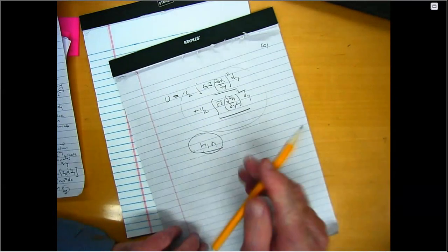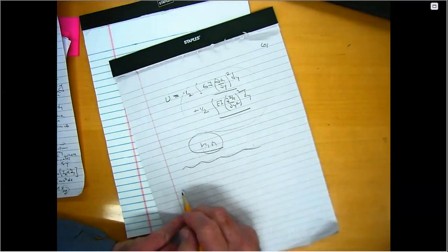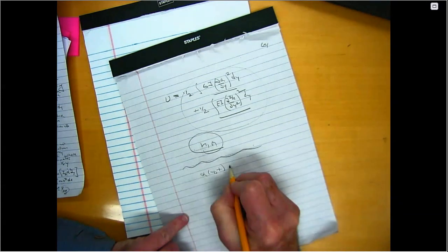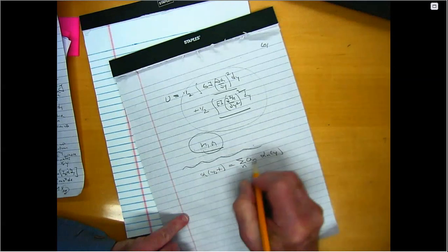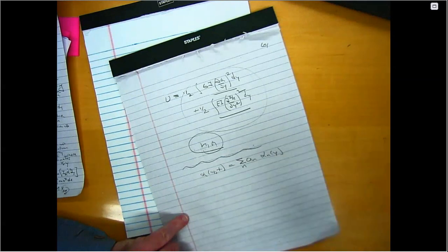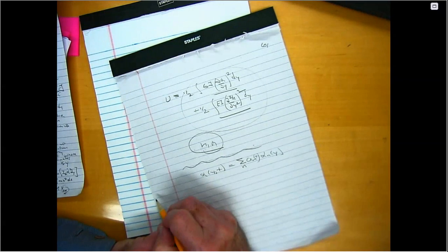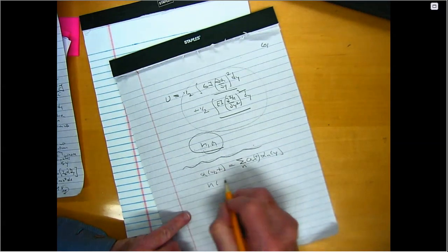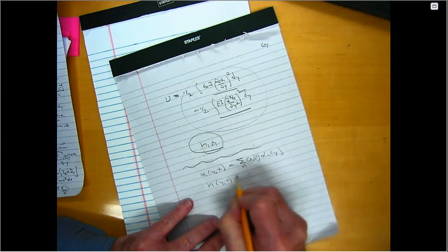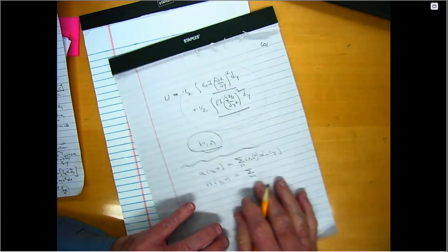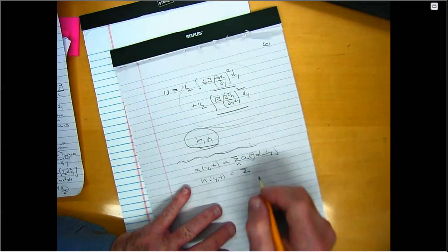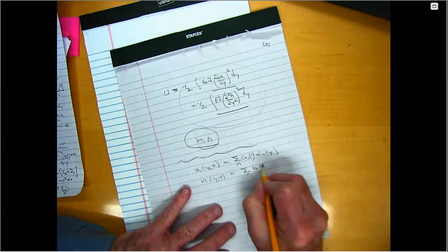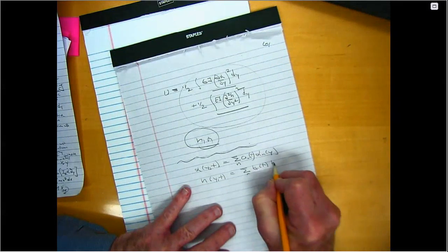Okay. Or I could use Rayleigh-Ritz. I could take alpha, a function of y and t, and write it now as a summation over n of a sub n times alpha sub n of y. But now I'm doing dynamics, so the a's have to be functions of time. And h of y and t, another sum, I'll use a different index, m. Well, let's call it r, because m, you might confuse with mass, right? r, b sub r, a function of time, times h sub r of y.